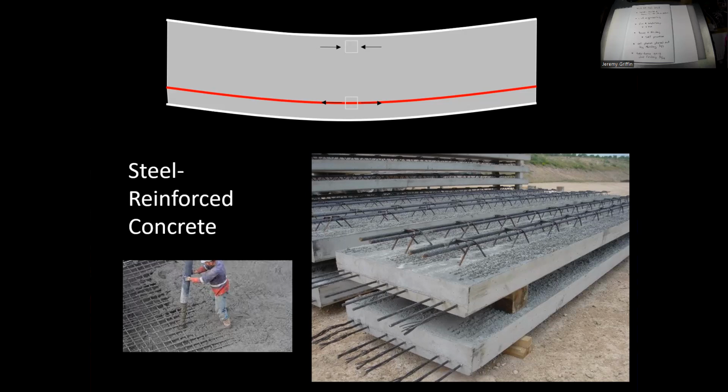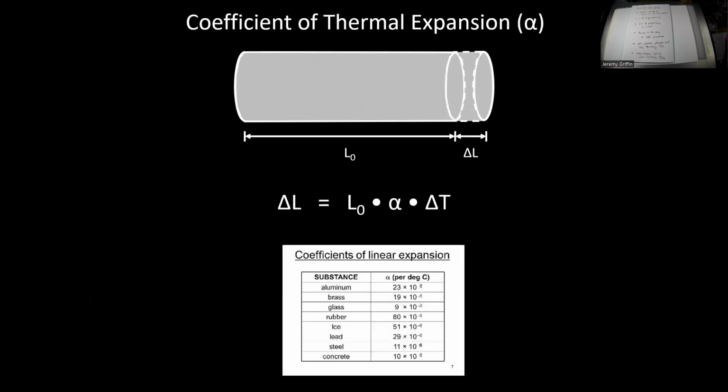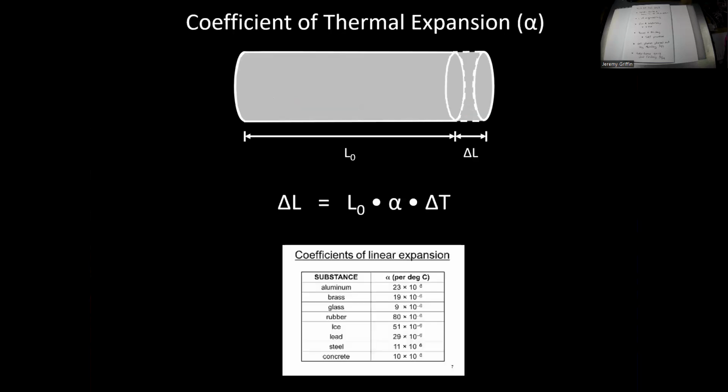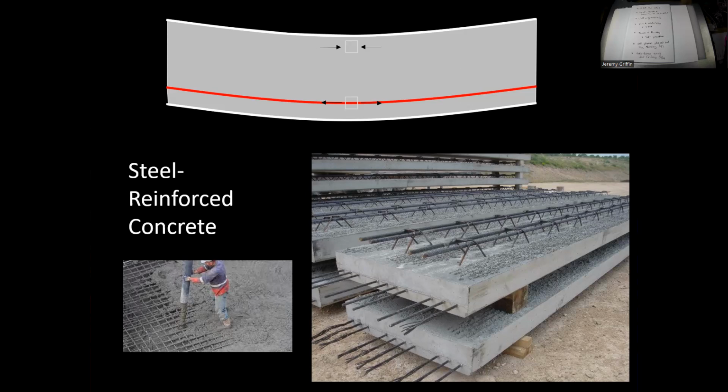And you guys can see it here, right? That steel rebar is embedded in that concrete. So now you have a composite material. And the fact that, go back to the last slide, the fact that steel and concrete have the same coefficient of thermal expansion means that your structure, from day to night or summer to winter, as things cool down or heat up, these two materials will expand and contract together, which means it's not going to all crack apart. Again, it's a complete luck of the universe that happens to be the case, but it is. So yeah, lucky us. We get to be on the second floor because of this weird thermal expansion property. Yeah, so lucky us.